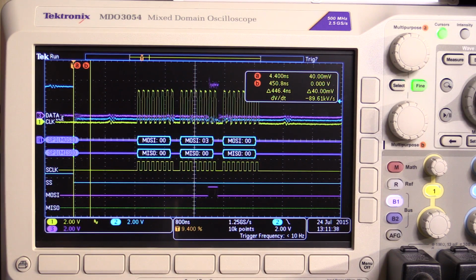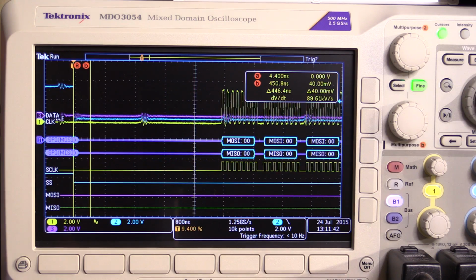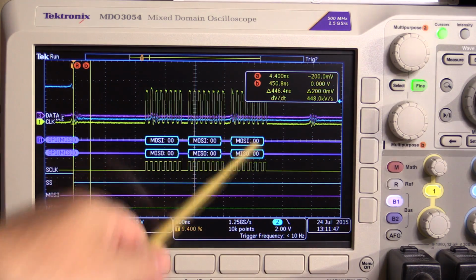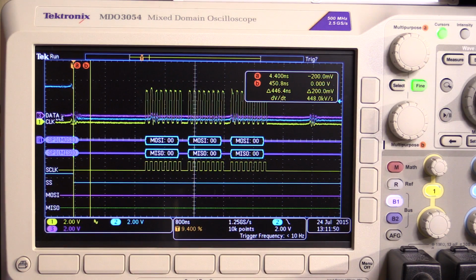So if I click both of them down to unipolar, you'll see that now I'm outputting control register 0000, which is now powered up, but I'm in unipolar mode. So both of my DVMs, or my channels, would now go from a 0 to 10 volt scale instead of a -5 to +5 scale, based on how I've got this currently configured.